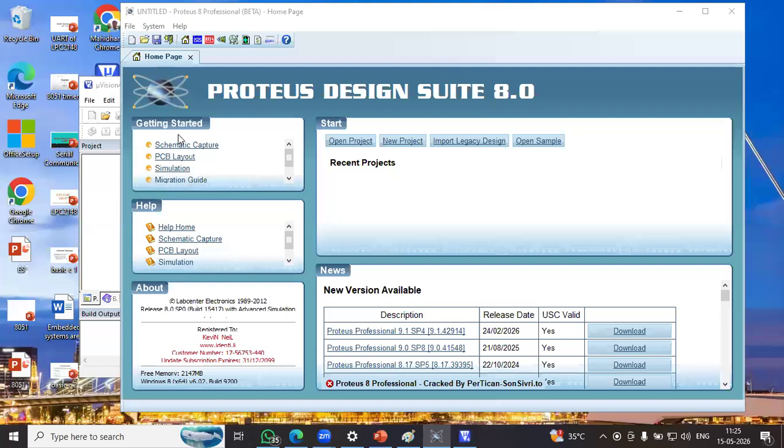Okay, guys. So right now we are using a simulator, so there is no need to connect the resistor for the LED, but in real time, you must add some resistance value to protect the LED. So now I completed the topic, that is interfacing an LED to a microcontroller. Today our main agenda is just to interface an LED to the microcontroller and blink the LED. So that is the main agenda, right?